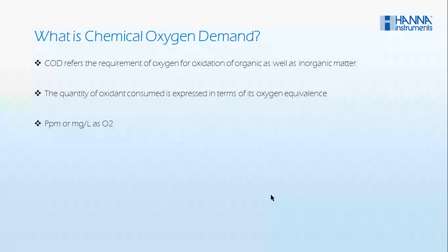It gives you the requirement of oxygen to oxidize the organic and inorganic matter by an oxidant, and the quantity of oxidant consumed is expressed in terms of oxygen equivalence. It is every time represented in the form of ppm or milligrams per liter as O2.